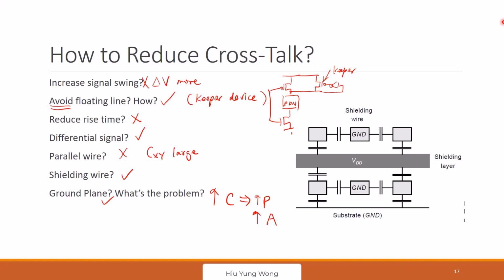Let me say this. Maybe I'm not good enough to answer this question. I don't have experience. But what I'm saying is that at least you need to fulfill what I'm talking about here. If you have a register, you're doing the clock, the most important thing is the register, right? You need to copy the data. There are two things. One, you don't corrupt the data in between, that is the noise, all this coupling. Second, you need to meet the timing constraint. And if you have an analog circuit, then you think about why you have a clock in the analog.